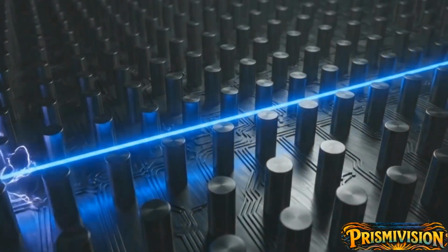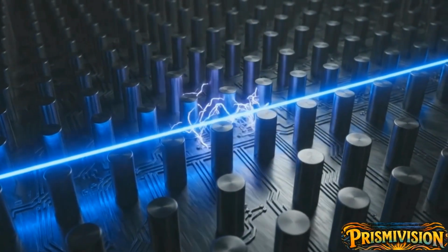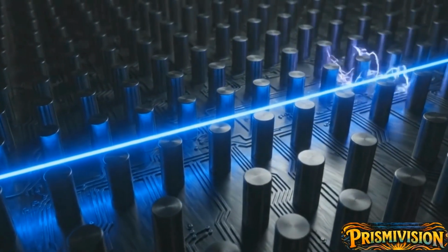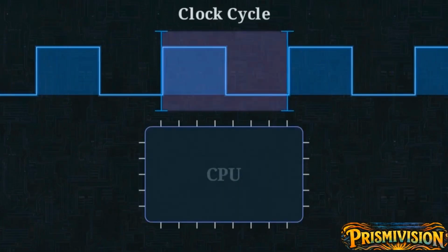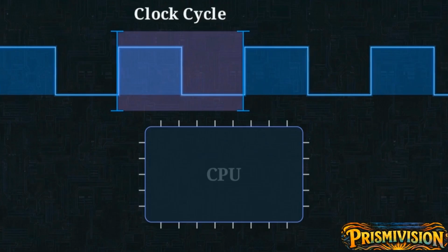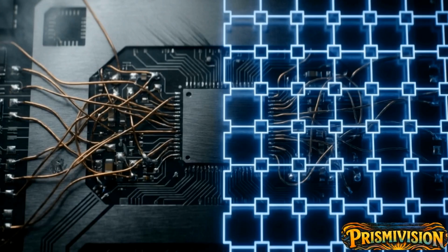To enforce these rules, engineers use a master clock. It is a continuous, rigid electrical pulse distributed across the hardware grid that forces every isolated component into a single synchronized rhythm. The discrete time interval between these pulses is called a clock cycle. It acts as the fundamental unit of time for the entire machine. The clock does not compute data. It enforces a mathematically consistent rhythm onto the messy physics of the hardware to ensure system stability.